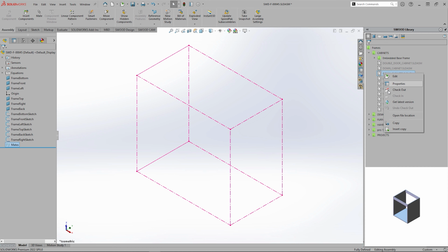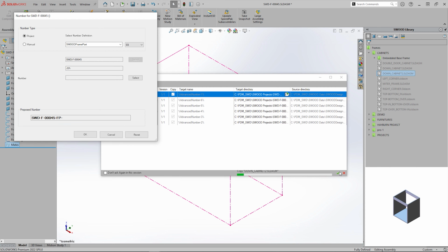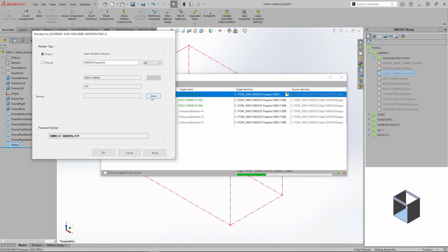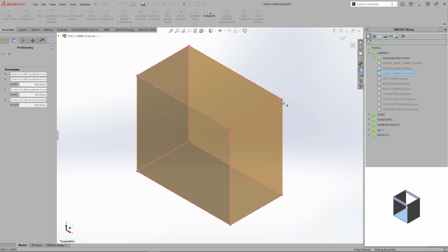Serial numbers can be made more complex by using the Advanced Numbering add-in. This allows the user to select which serial number should be used for each part, and creates a more tailored part number. An example of this could be to append project information to the serial number, creating a consistent naming scheme across all parts and assemblies in any given project.